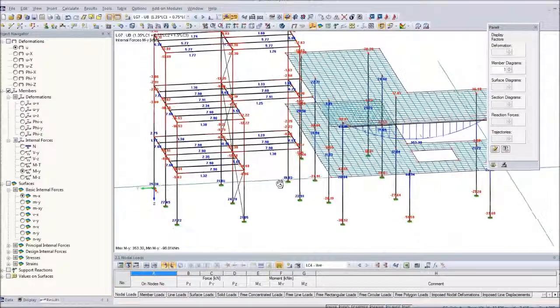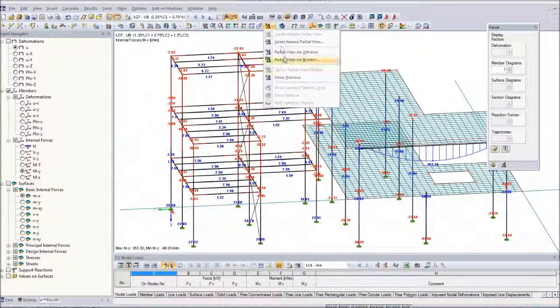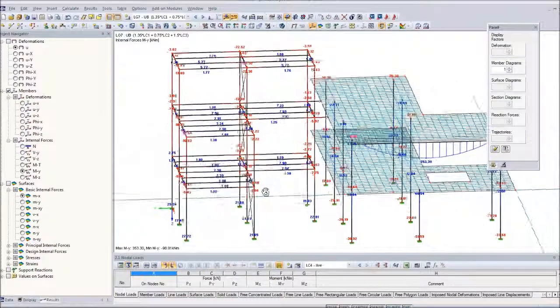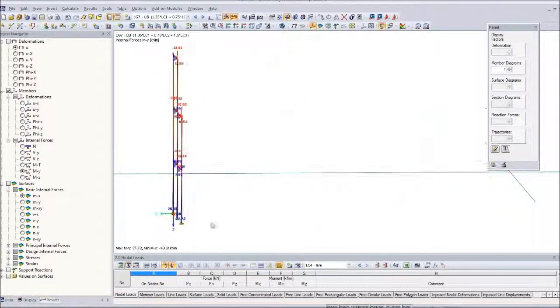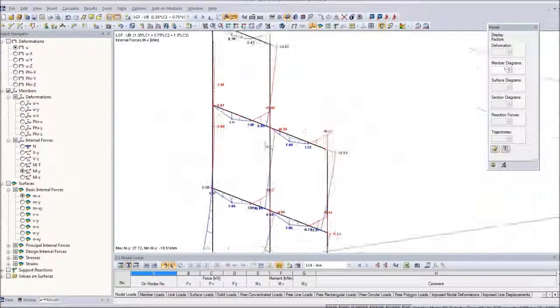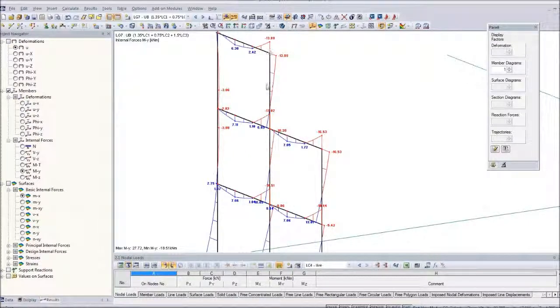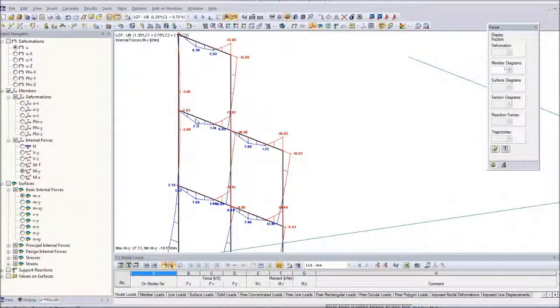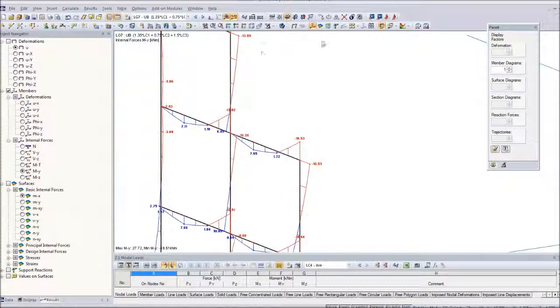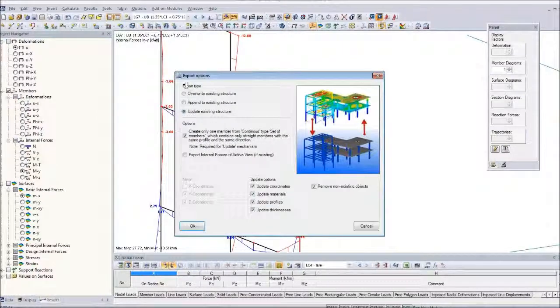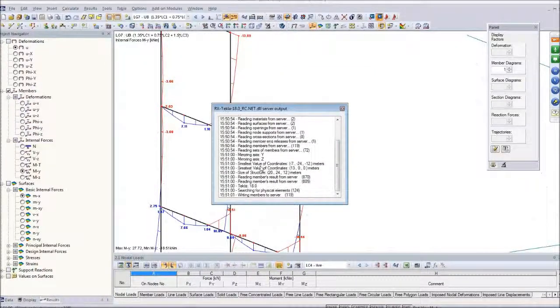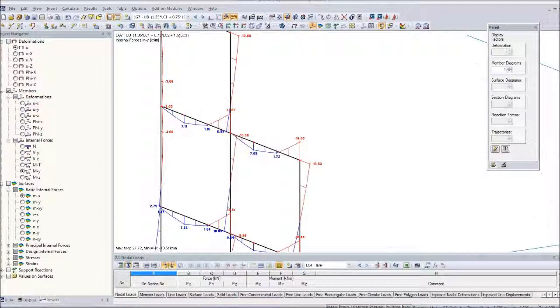At the end, I'd like to show you a few more things before we go on to some questions. For example, what we also can do is we can update the tekla model, the tekla database, with some results for internal forces. For example, I see this beam here, and if I update now the tekla model with my load group results, load group 7, I enable results. We will also write in the tekla model the results.